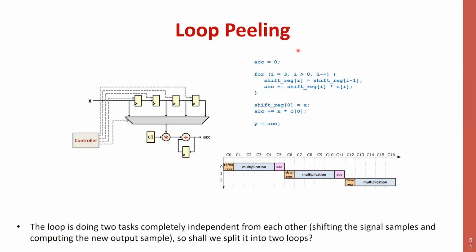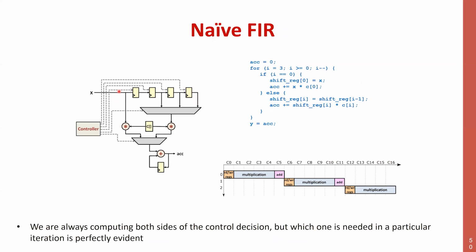Unfortunately, because of the same reason that we were discussing with VLIWs, the space of how to apply all these possible rules is too big, so you have to do it yourself. So this is manual loop peeling. You rewrite the code this way, and the hardware that your HLS tool most likely generates is this one, which is slightly different in the sense that now, let me go back to see the difference, right?